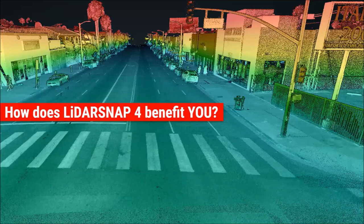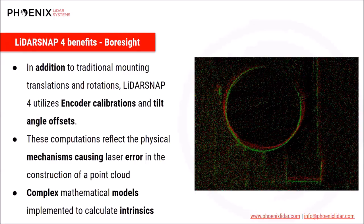So let's go into a lot of the benefits of LiDARSnap 4. Let's start off with the boresight again. While traditional boresighting is normally done with just mounting translation and rotations, LiDARSnap 4 also utilizes encoder calibrations. So the center of the encoder not matching the spin axis, as well as the angle of the laser and the spin axis perhaps being slightly off. LiDARSnap 4 allows us to very carefully calculate and calibrate those parameters that are inherent in every laser system, but not necessarily addressed in every LiDAR calibration software.